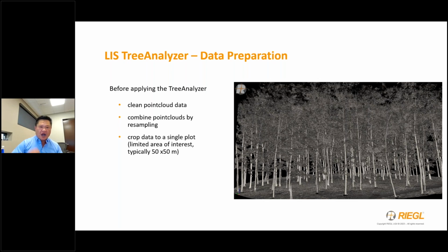When it exits, it is a perfectly circular beam, and when it hits a shallow-angle object, the beam becomes an elongated ellipsoid. That produces a much different reflectivity and, of course, deviation value. So you've got to clean it up, and we have a workflow for all of this as well.